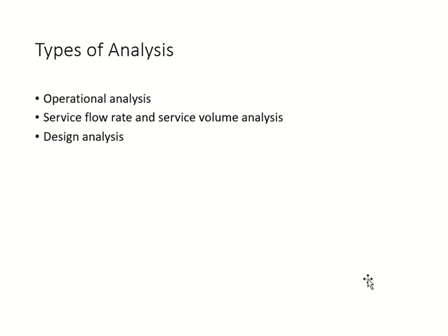So if service flow rate means maximum flow rate for a level of service, service volume means what? Maximum volume for a level of service. Clear? Every level of service has a maximum flow rate and we call it what? Service flow rate. And every level of service has a maximum volume. We call it what? Service volume.